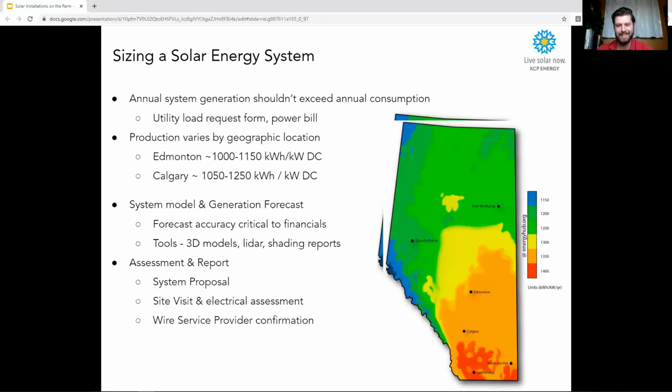It's going to be maybe 10, 11% less, but not a massive factor. So typically we say anything facing west, south, or east, or anywhere in between is perfectly fine. You just want to get away from situations where the panels might be facing northeast or northwest or fully north, just because the production can be quite poor at that orientation.